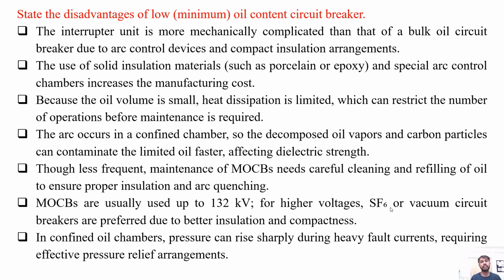State the disadvantages of low oil content circuit breaker, or minimum oil content circuit breaker. The interrupter unit is more mechanically complicated than that of a bulk oil circuit breaker due to the arc control devices and compact insulation arrangements. The use of solid insulation materials such as porcelain, epoxy, bakelite, etc. and special arc control chambers increases the manufacturing cost.